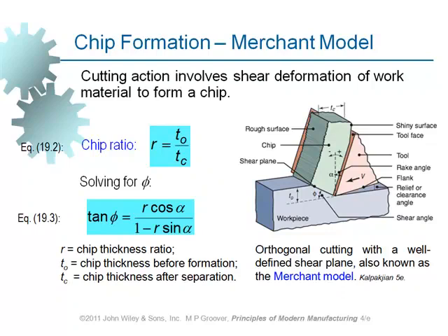If this is the horizontal surface, when I bring the top surface down, the tip of the cutting tool would be sharper. So as a consequence, a positive value for alpha would reduce the required cutting power, machining power, because it does produce a sharper cutting edge. And there is an important angle here, which is referred to as the shear angle, represented by the parameter phi. This angle does play a very important role in resultant machining parameters.